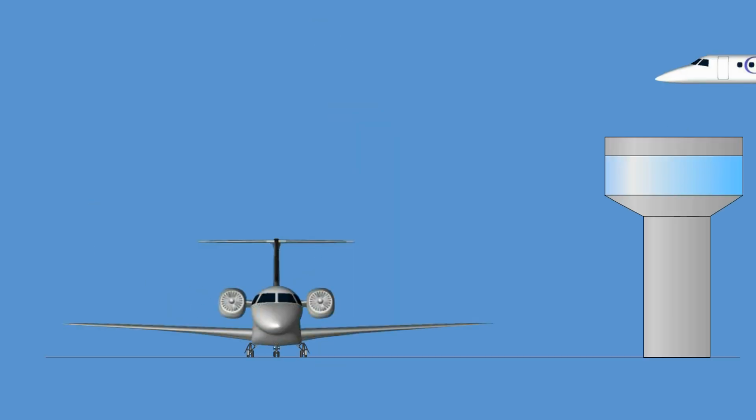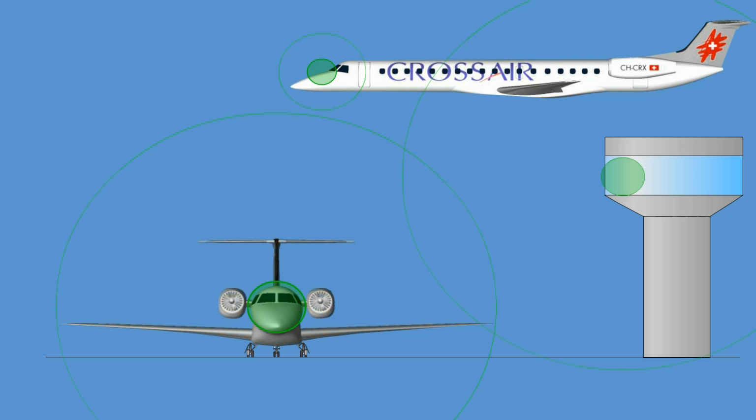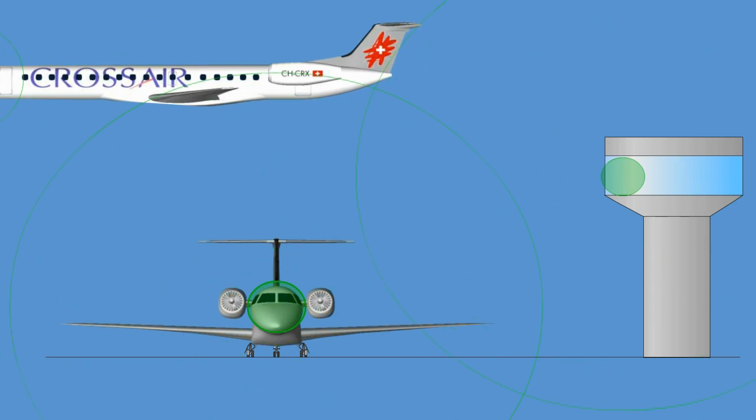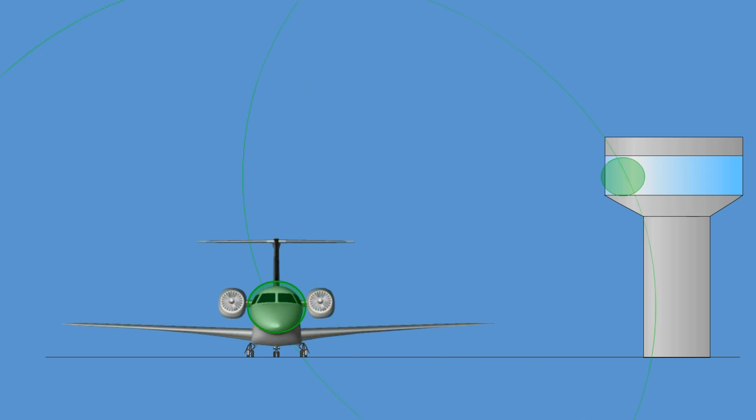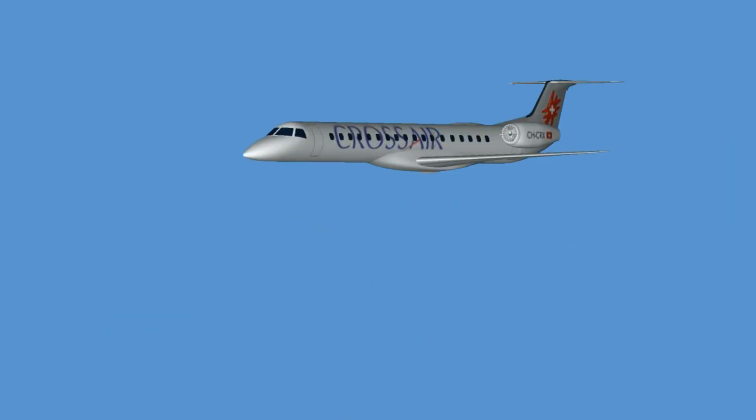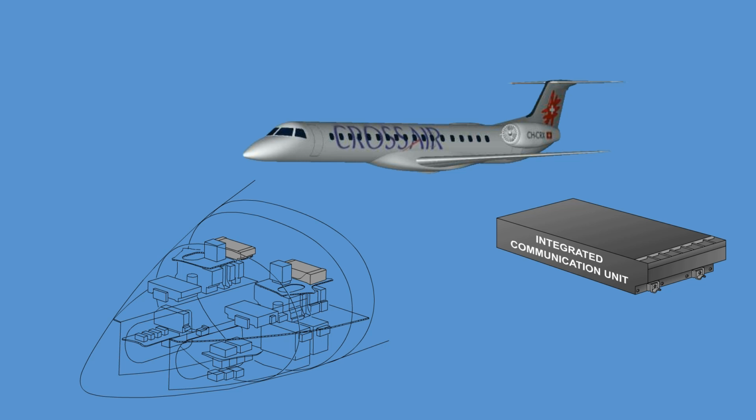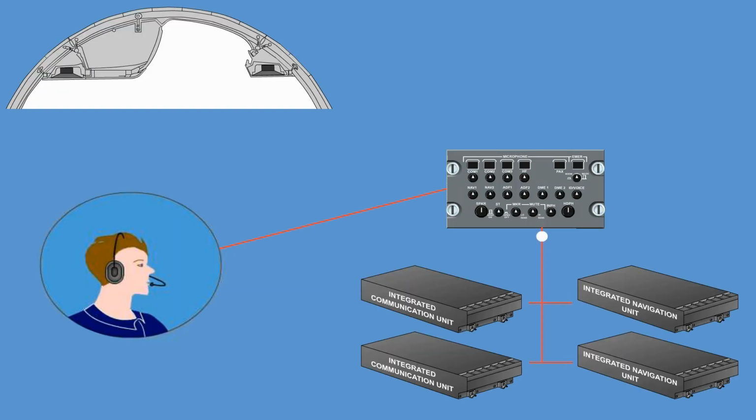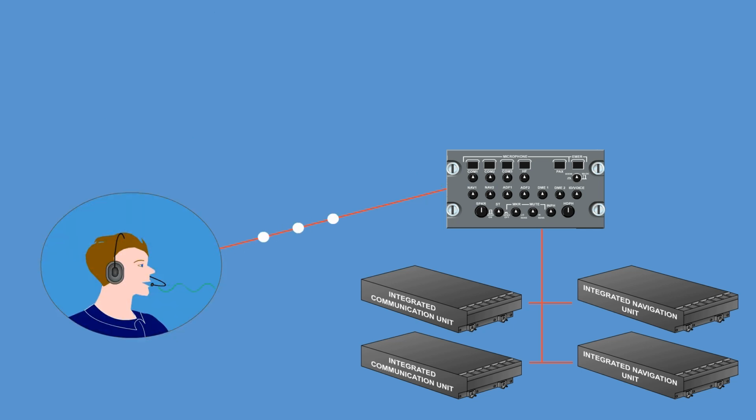It also allows for voice intercommunication via the aircraft radio communication systems, and monitoring of all audio outputs of the communication and navigation systems. The airborne audio subsystem controls the output of the communication and navigation receivers into the flight crew headphones and speakers. It also controls the output of the flight crew microphones into the communication system.